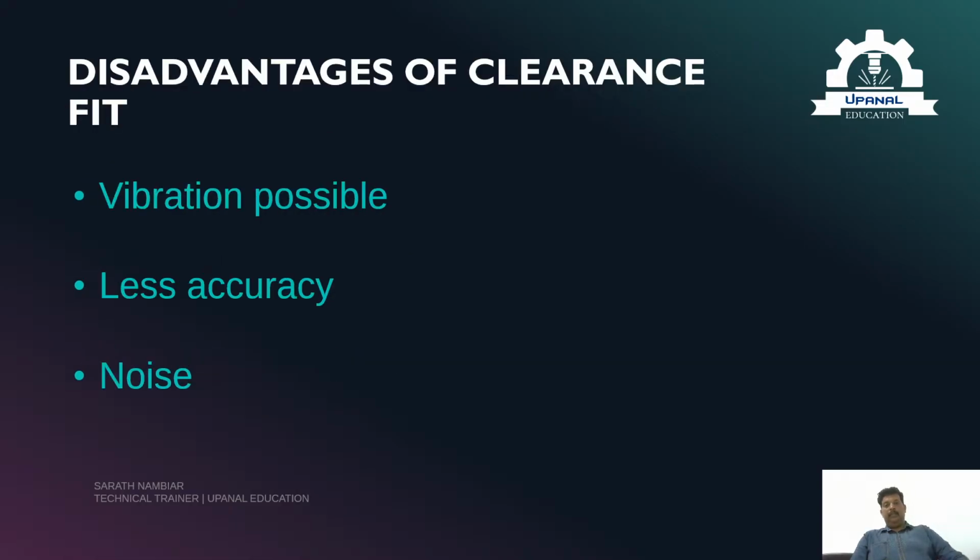Okay. Now, what are the disadvantages? Of course, everything has an advantage and a disadvantage, right? Now we are going to the disadvantages. Clearance fit has some disadvantages. If the clearance is too much, the parts may vibrate. If the shaft is too loose, the thing tends to vibrate. There may be noise, and the positioning accuracy reduces. So this clearance must be carefully controlled.